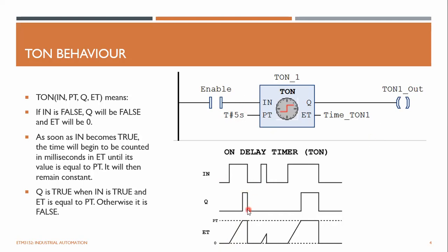Now in this example, you set the input to high, and the timer starts counting time, but you remove this pulse here. So you disable it or set this IN pin to 0. At the same time, the timer stops its counting and is reset back to 0, right? So you have to keep this always on until it completes its time counting.